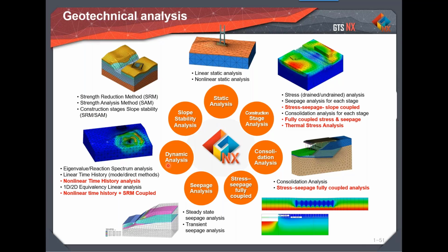In addition, you can do the dynamic analysis, wherein let's say you want to determine the frequencies of your model. You can go for eigenvalue analysis, or else if you want to simply do the response spectrum analysis, you can go for response spectrum analysis. If you want to calibrate your model using the 1D ground response analysis, you can do that. This is the same thing which you might have used in DEEPSOIL or SHAKE2000 software. In that software, there is an option called the 1D ground response analysis. You can do that directly in the software itself. And we have a 2D equivalent linear analysis as well. So this is in addition to the 1D ground response analysis.